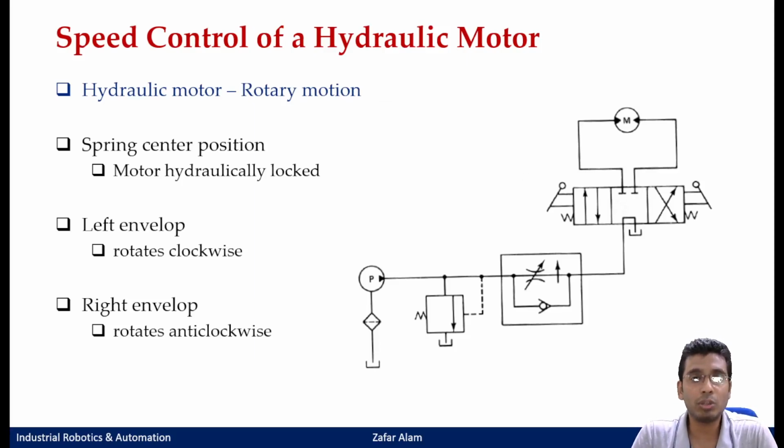Now, although I said that in this entire module of pneumatics and electro-pneumatics, or hydraulics and electro-hydraulics, I would be focusing more on linear motions or linear actuators, however, just in today's session itself, I'll be giving just a glimpse of how your rotary actuators or hydraulic motors would get controlled. So what picture do you have here? This is your power generation, then again your relief valve. This is your 4x3 DCV, spring centered, manually actuated, and this is a symbol of your hydraulic motor.